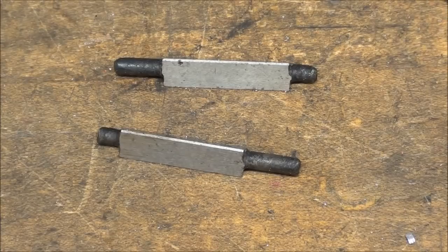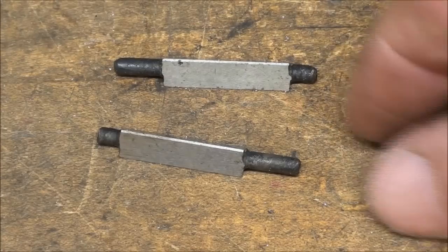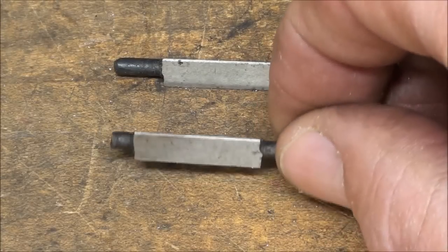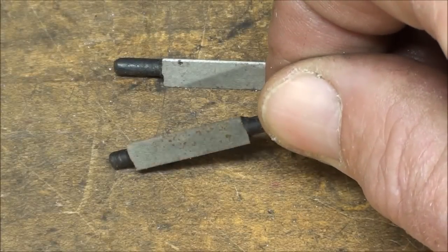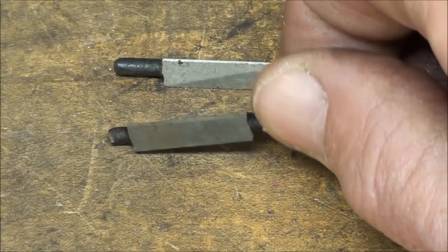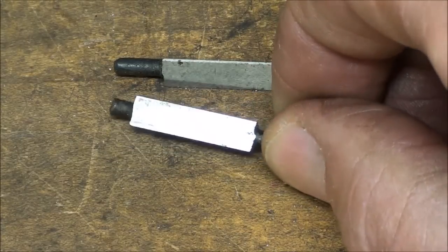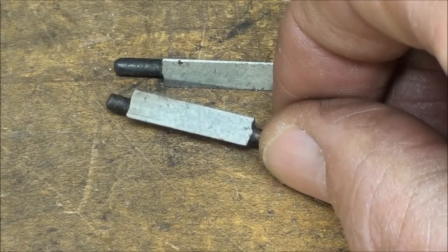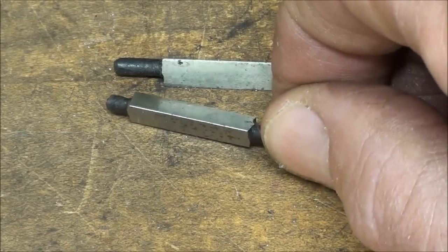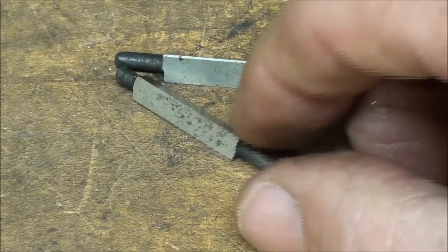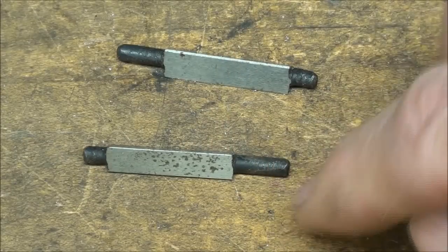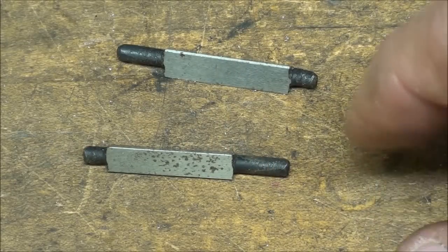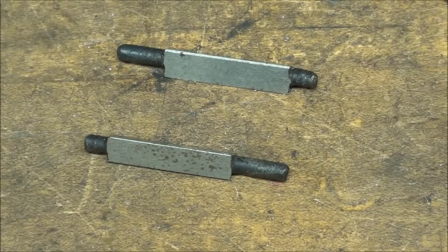And here's the final method, and I'm going to tell you about them, but I really can't do it, and I'll tell you why. These are called thread triangles, and they're little hardened triangles of a certain size. And these were supposed to be easier to use than the 3-wire system. And originally these came with a little rubber harness that could go around these pegs on the end, and then it would slip over the anvil and it would stay on the micrometer.